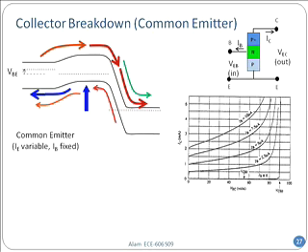Now, the more emitter current it has to push, what will happen to VBE? The VBE must be larger, or the barrier must be reduced, so that it can accept that current, right? As soon as it reduces the barrier, what will happen? It will forward bias the junction, more electrons will flood in, and more electrons flooding in means more impact ionization.